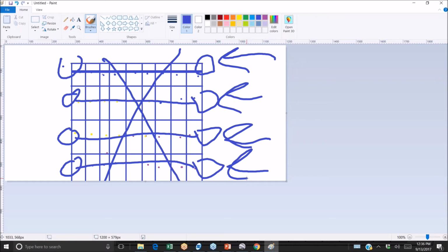So that clip tolerance is like Apple making really tight tolerances on their products so that when you plug in your iPhone charger, it stays in, whereas with Droid, you plug in the charger, and after about 6 months, it starts becoming really loose, and you have to get either a new phone or a new cord. The MC4 connectors are more like Droid than Apple, where depending on which ones you pick, the connections might not be completely tight, and if they're not made tight, they'll start arc faulting and triggering an error in the inverter and shutting down, especially during the commissioning process.